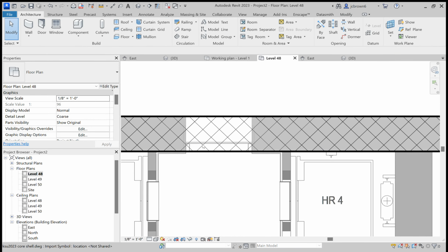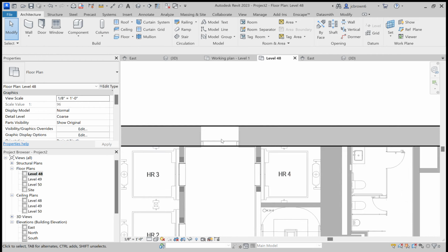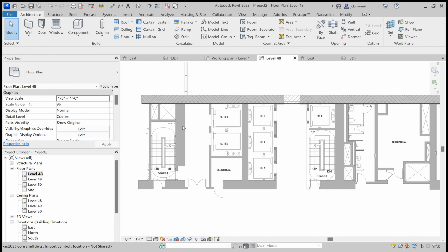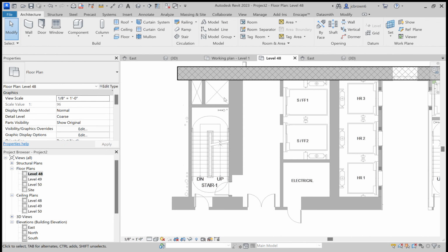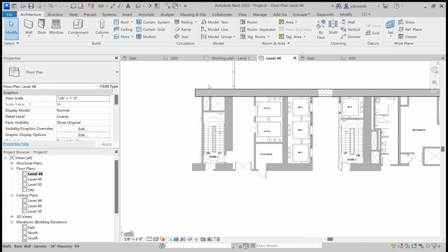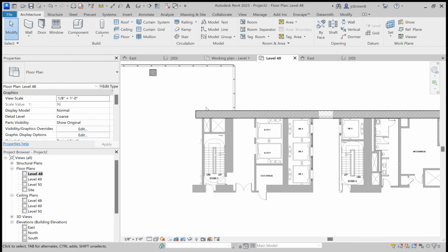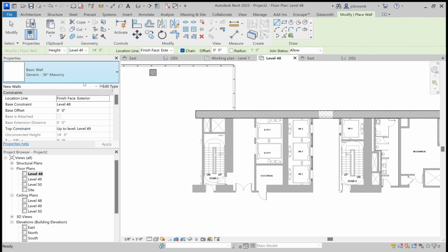And notice how all of our walls are on 50% transparency, so we can still see where the window is when we need to place that later. So you'll go in and do this for all of the walls. And you will notice that some of these walls are going to need to have drywall later on this side, and this side. So you will have to create and duplicate some of these walls.